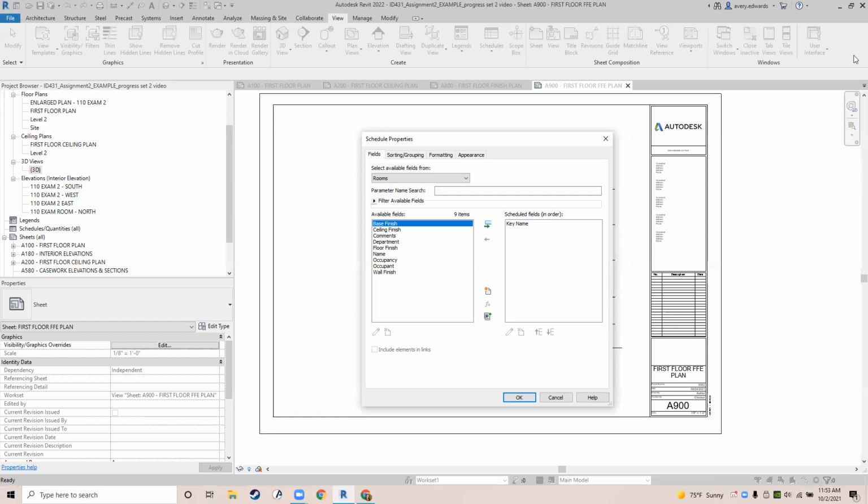So instead, when you place all those model components, say I placed a Steelcase desk that has 200 pieces and parts, little individual model components, I don't want to tag all of those, right? That's not my intent, because I'm not the one picking out those parts and pieces. I just want to call it a desk as a whole. So instead of smart scheduling all of those pieces, we just want to create a dummy schedule where we can manually put in one desk.